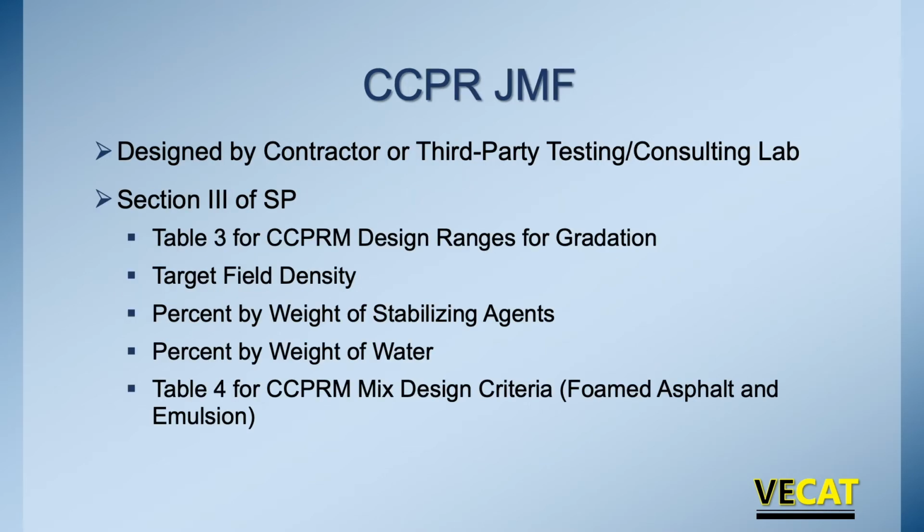So what's in the job mix formula for the CCPR? Well, the contractor or a third party designs the mix. They'll take the RAP, they'll take a stabilizing agent, they may take an additive like cement, a little bit of water, and may need to add a little bit of virgin aggregate, and they'll put it together and develop the job mix.